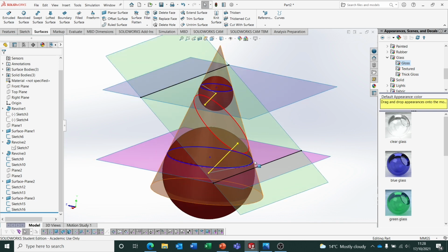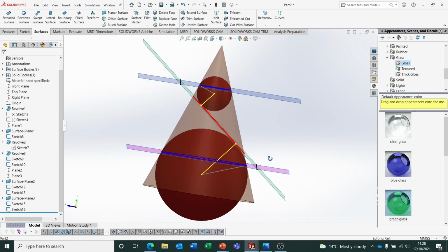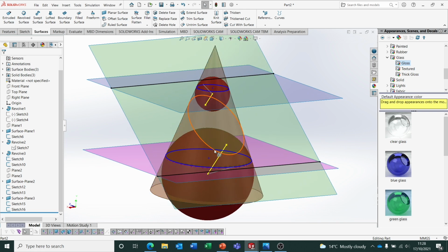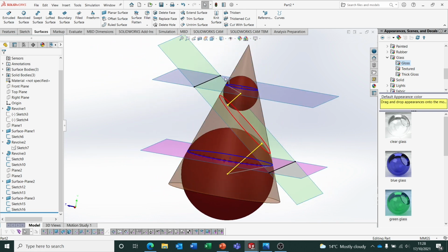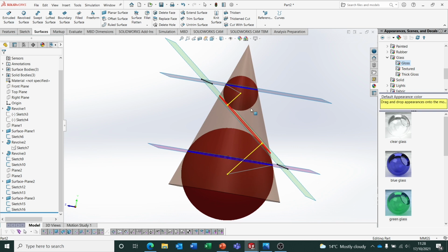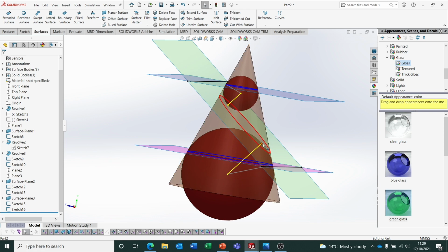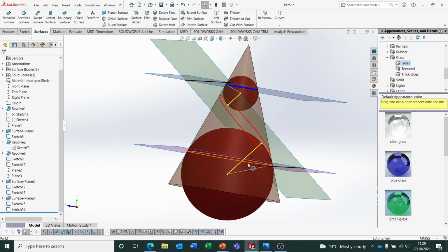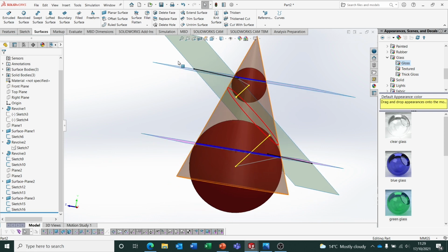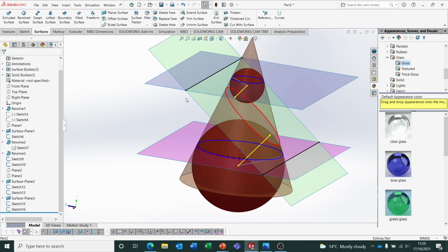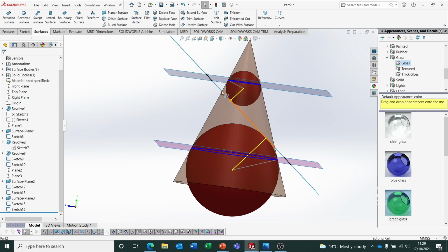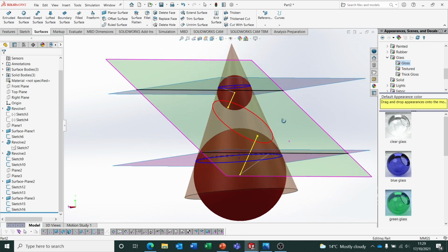So a cutting plane, and the cutting plane is between the angle of the cone and the horizontal line or the horizontal plane. Okay, so that's cutting through the object, gives us an ellipse. Focal spheres are spheres placed inside the cone, in contact with the cone and in contact with the plane. Where they contact the plane give us the focal points. Where they contact the cone give us the height for these planes, which create the directrix then. So where they cut through the cutting plane then give us that directrix.